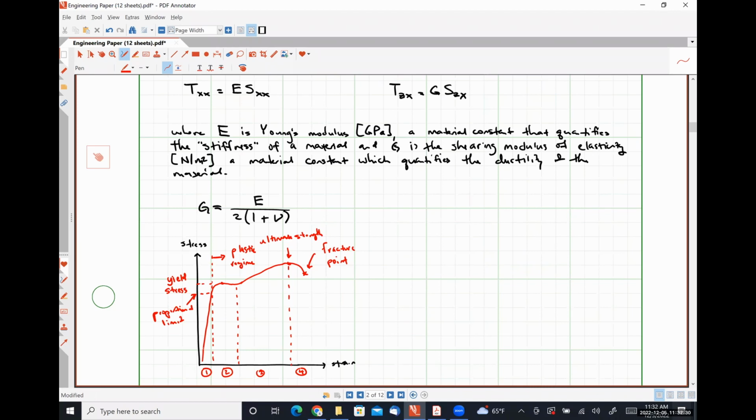The necking deformation is heterogeneous and reinforces itself as the stress concentrates. So effectively, it's a positive feedback system where the more we do it, the more necking occurs until finally the fracture point is reached and we have broken our material. Okay, so our sample has completely failed.